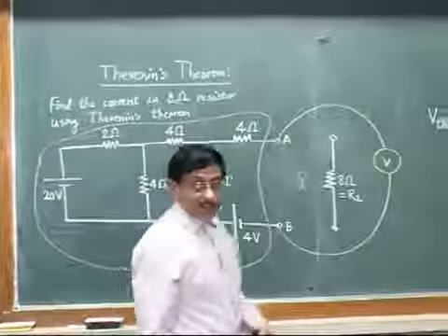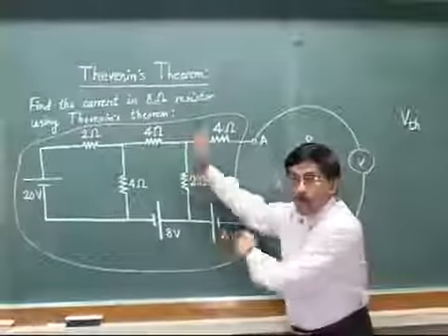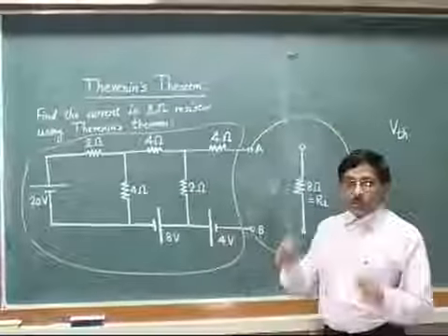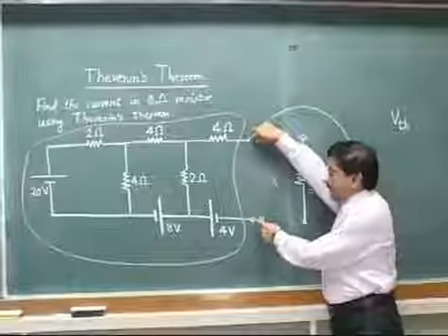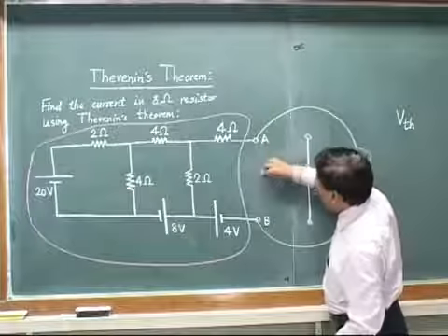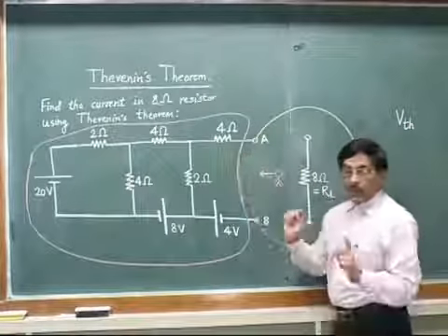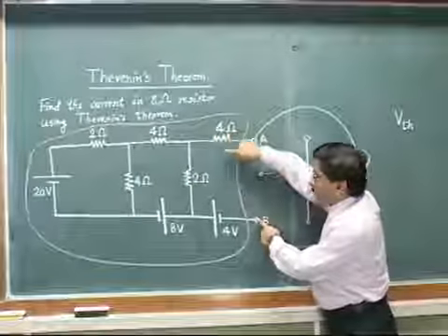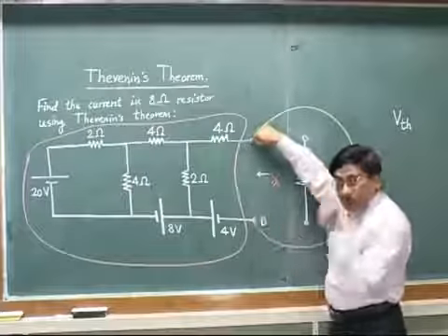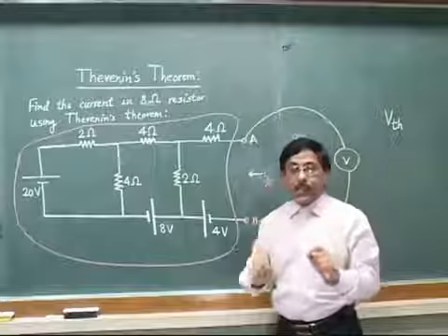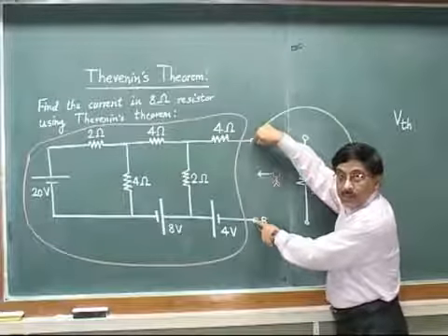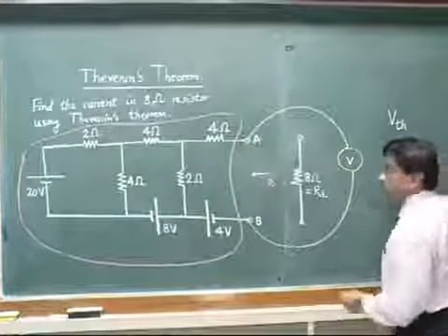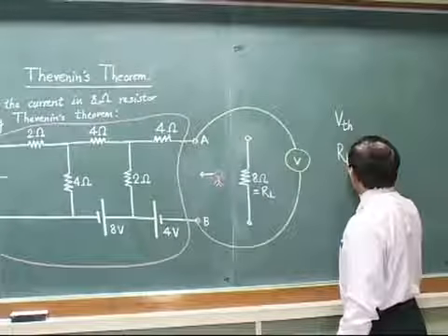Now further Thevenin said that that is not the only thing which was there in this red box, but the red box also contains some resistances connected in certain fashion. So Thevenin said that if you look inside these two ports, suppose this is me and I am looking inside the circuit, whatever is there in the box, what will I find? I will find that this entire network of resistances will give one equivalent single value of resistance between these 2 points, some single resistance between these 2 points. We call this resistance Thevenin's equivalent resistance, or say RTH.